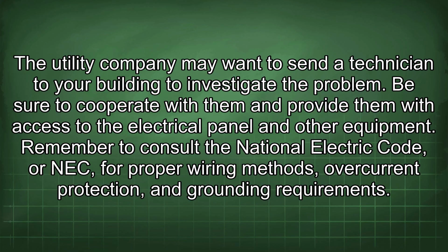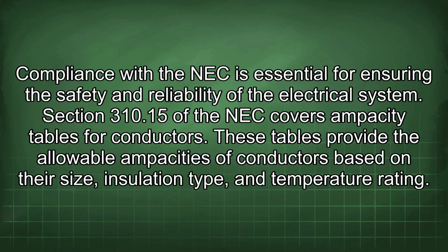Remember to consult the National Electric Code, or NEC, for proper wiring methods, overcurrent protection, and grounding requirements. Compliance with the NEC is essential for ensuring the safety and reliability of the electrical system. Section 310.15 of the NEC covers ampacity tables for conductors. These tables provide the allowable ampacities of conductors based on their size, insulation type, and temperature rating.